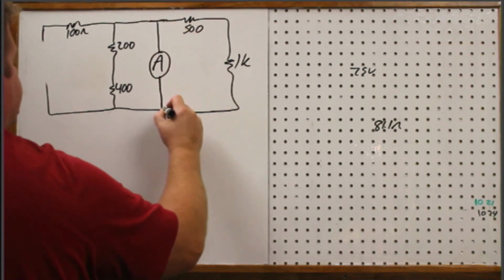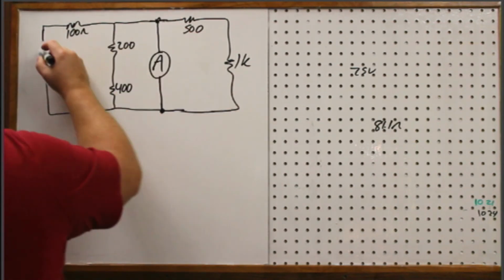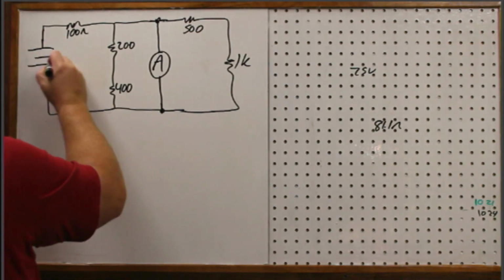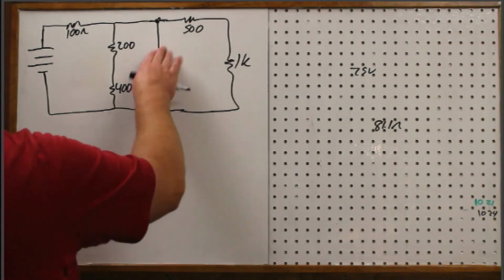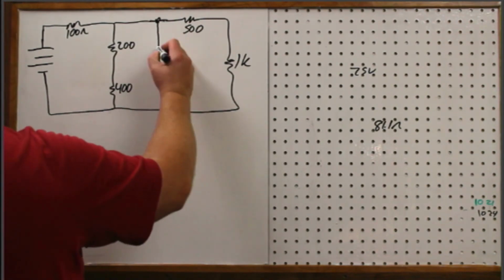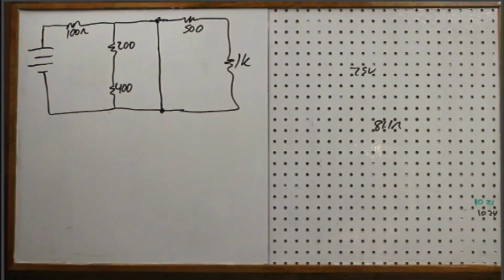This is something you should never do, by the way, in real life, right? Because you will damage the meter, because somewhere you're shorting something out. Okay? So what you're doing, and remember, you can look at this as if it were just a short. Right? We know that the ammeter has, what, less than 10 ohms?